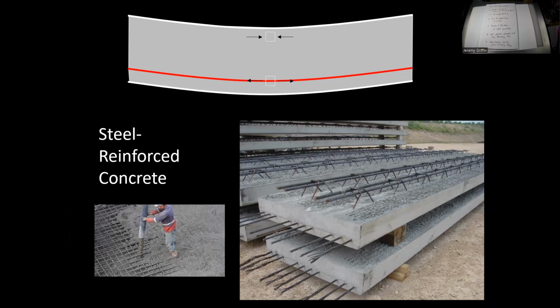Concrete has no tensile strength. So, I mean, basically none. So that's just going to crack and fall apart immediately. And that's the problem the Romans kept running into. But you throw in some steel rebar, that steel has a tensile strength that could be like 10 times the compressive strength of concrete. So yeah, you only need a little bit of steel rebar.